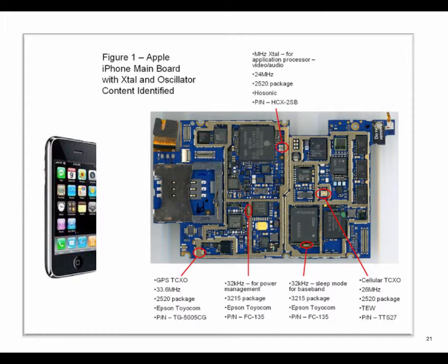So the cellular network operates in a highly synchronized fashion within a certain frequency band. But then you do put radios to sleep, and while they're asleep, you don't need that power-hungry high-speed clock, so you can switch to a sleep mode clock over here. And then finally, there is a clock driving the application processor, Apple's A6, A7 type devices. So you see, even in a simple device like this, we have 5 or 6 oscillators. And more importantly, these oscillators often come in separate packages and not sitting on your chip.